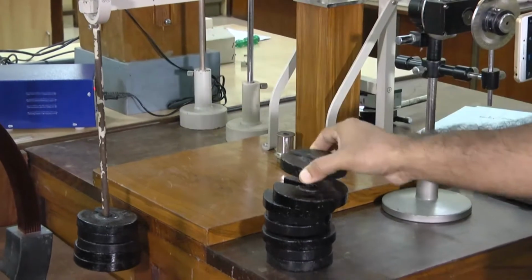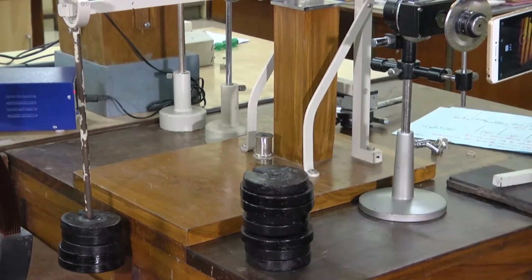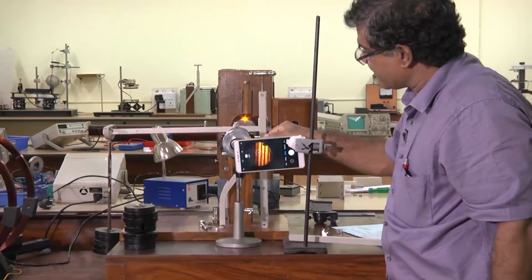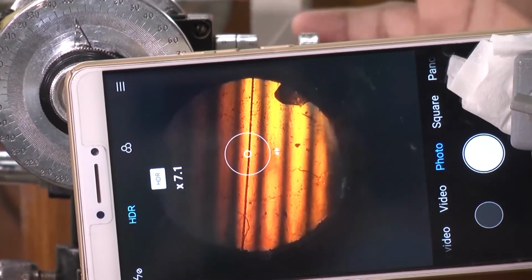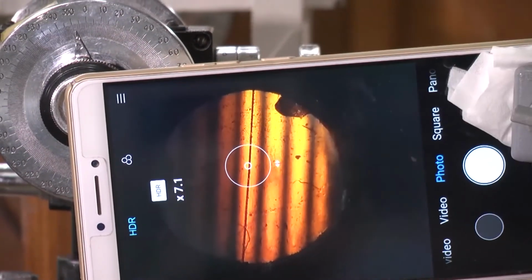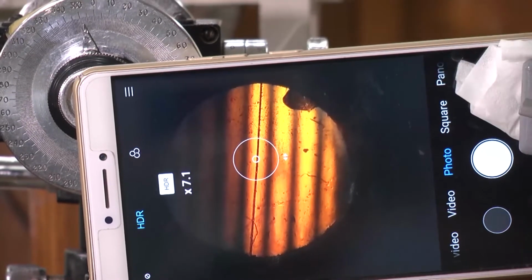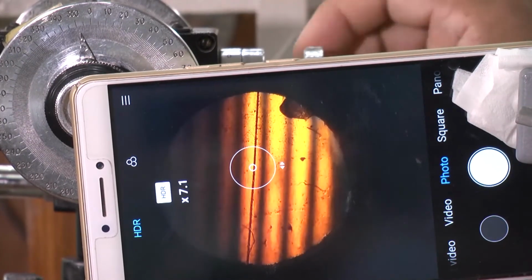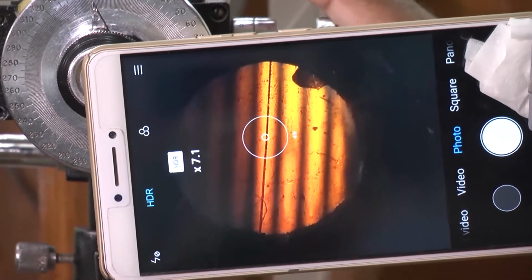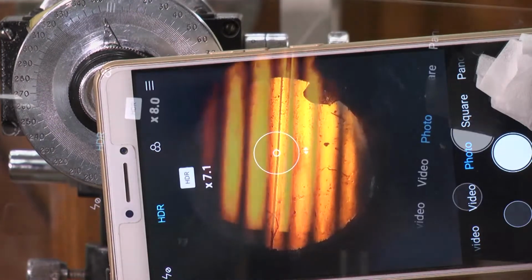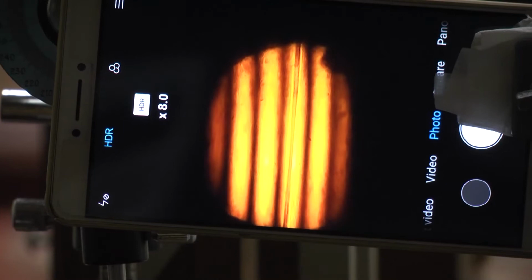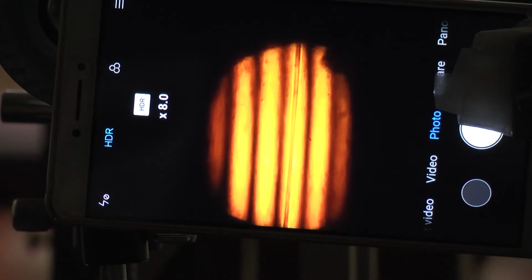During unloading also there will be a shift of this, and then you should bring it back to this and then take the reading. So, this way, during loading and during unloading, we see how much the shift is. With this Babinet compensator, that shift we can measure. Whatever I am showing here is slightly difficult to catch in the camera, but it looks very sharp and better, and there you can see it precisely.